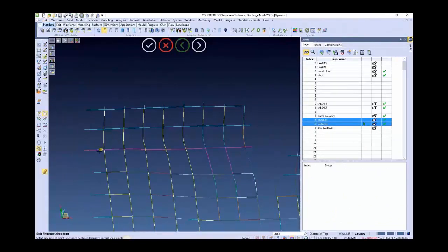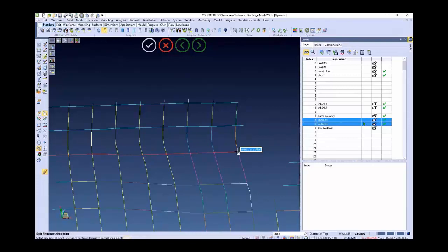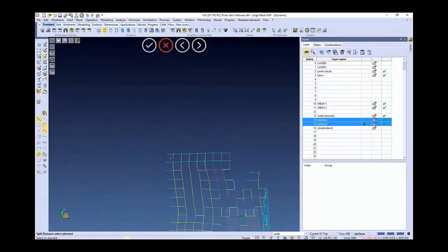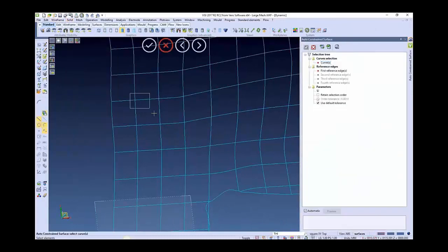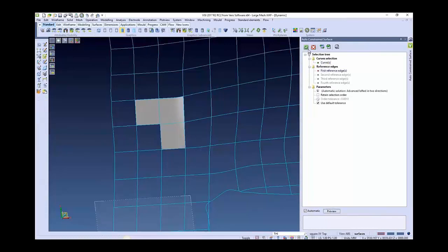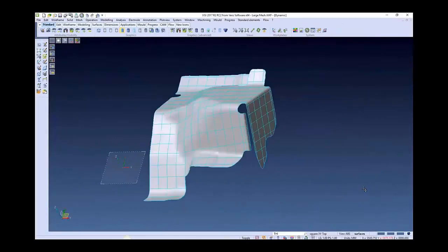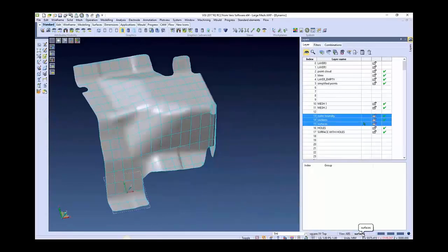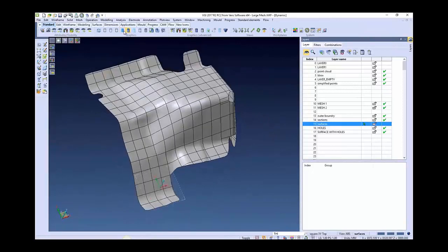Now we can split the element there by that point, making sure we actually grab the correct points. As you can see, zooming in when we need to grab that specific point. Now, once we've done that, with our auto constrain, we can start building the surface. So that reverse engineering is kind of a stepping stone for us to get to this point. And when we're done, we've got a whole surface. From mesh to surface, using that reverse engineering.